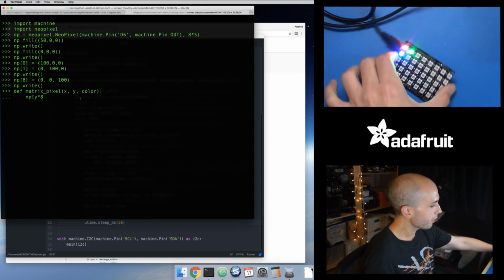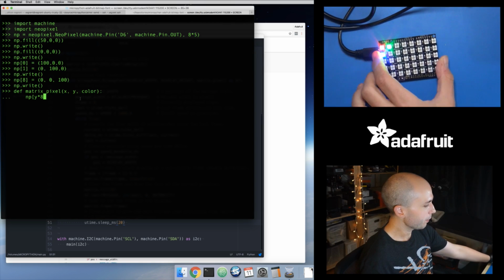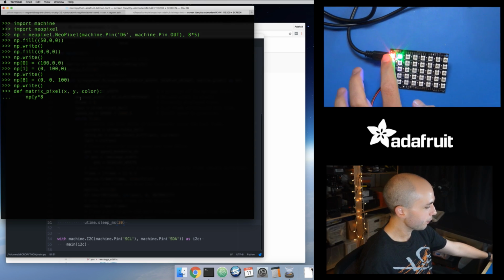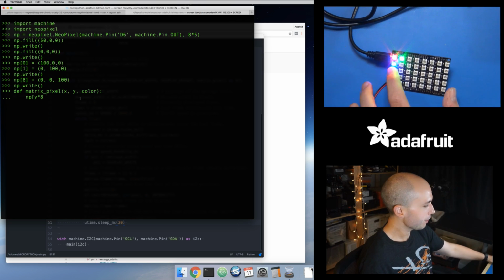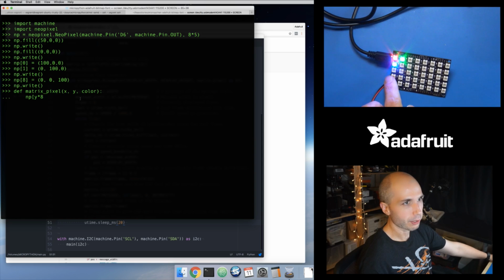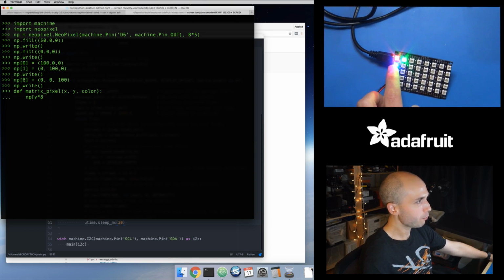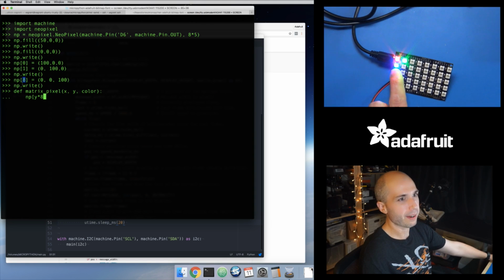So basically I'm saying, imagine let's put the display in this orientation. So if I want to say position 0, 0 up here, let's make something more interesting. How about this pixel below here? So the blue pixel right here is position 0. It's in column 0, the X position 0, but then Y position 1. And now remember, this is pixel 8, index number 8. So I want to do some transformation that converts 0, 1, X position 0, Y position 1, into just the single value 8.